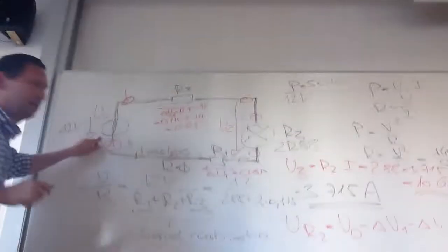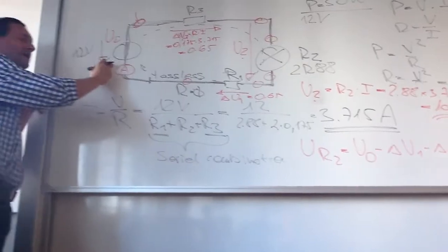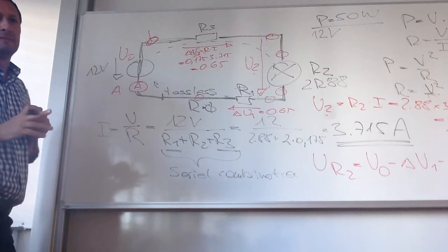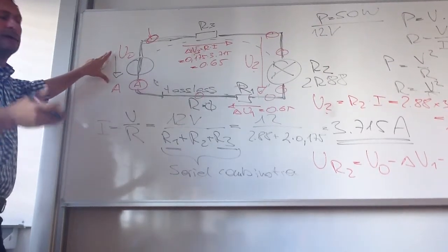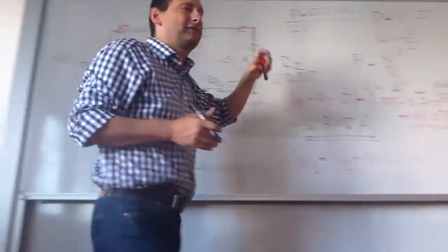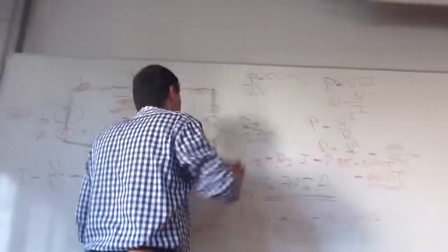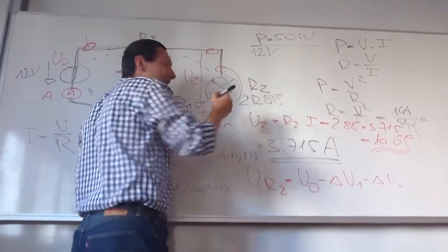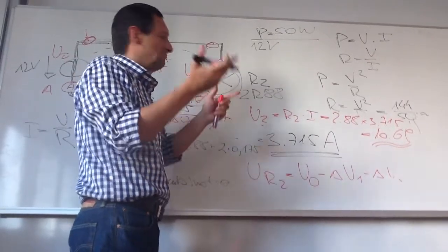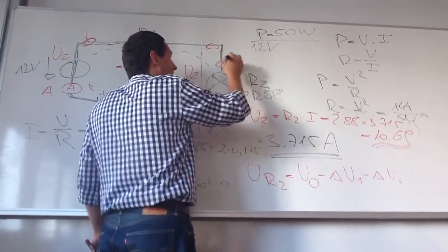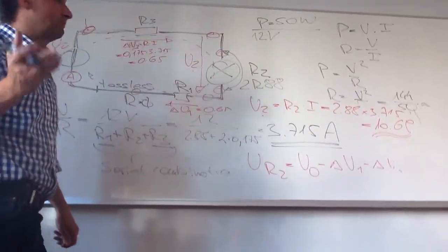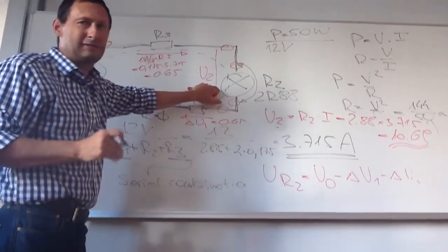Because here we got stable conditions. No matter how long you do your experiment, you will have 12 volts. Okay. So that's why we normally use power supplies. And the other fine thing with power supplies is maybe it can happen you do a short circuit here, you make a miswiring, it happens sometimes. Then there is no limiting factor for our current, because here the bulb is limiting the current.